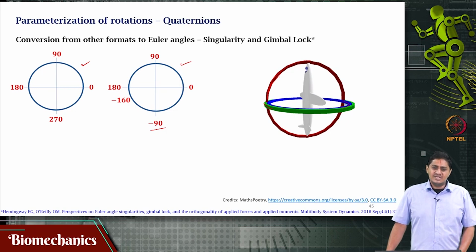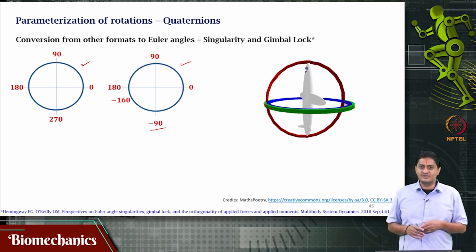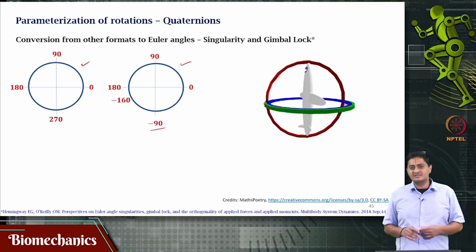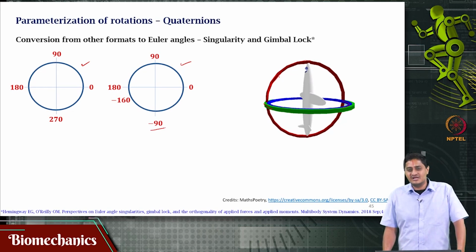So, is there a particular orientation where you will not require that middle gimbal to ever go above, say, 65, 70 degrees? If there is that orientation, that is where you align that gimbal, right. So, that is important. So, the middle axis should be aligned to that axis that does not require more than around about 75 degrees of orientation change.